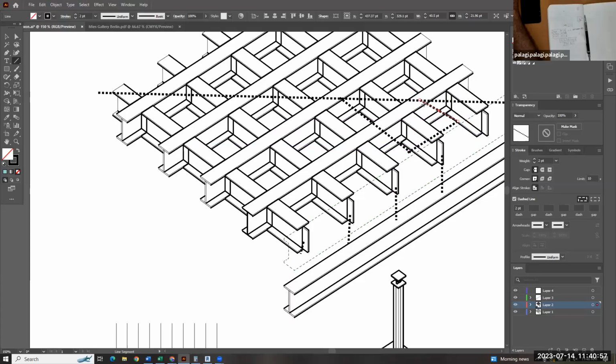Well, that's 12 feet, and then that's half of 12 feet. So it's 144 plus 72. 144 plus 72 is a little over 200, times 130 pounds per square foot. Right. And so this is where diagrams can become pretty rich just with those basic numbers, because you could show, hey, this is what makes it unique. Each one of these is actually loading this beam differently, which although it seems very uniform, that edge beam is actually having to take a lot of different weights across it.